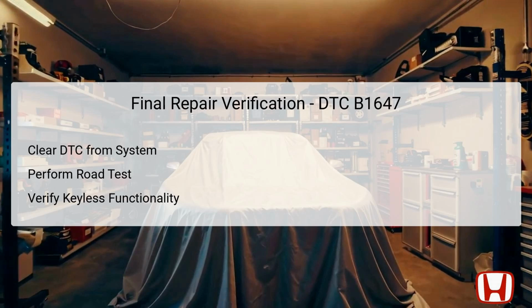After clearing the DTC, conduct a thorough road test while checking if the keyless entry system operates effectively without any interruptions. It's essential to verify that both locking and unlocking functions work as intended from the key fob, ensuring the original performance of the vehicle's electronic door locks has been restored. This final step confirms that the entire repair process was successful and that the vehicle is now free of faults related to the LF antenna circuit.